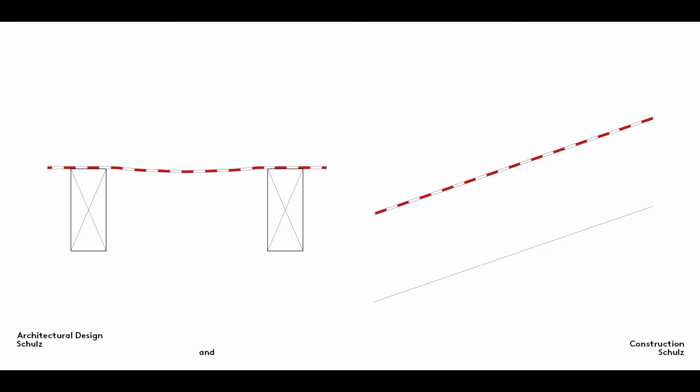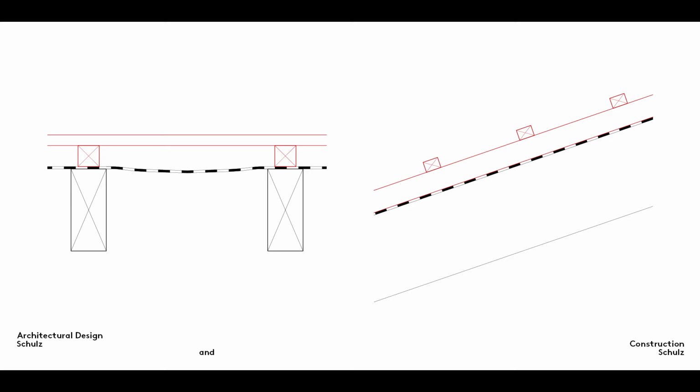The membrane is tacked or stapled onto the rafters so that it sags a little between them. At the next stage, the roofers lay the counterbattens on top of and parallel to the rafters to ensure that the roof is ventilated from the bottom up. The battens, sometimes referred to as the main battens, are then laid at right angles to the counterbattens. Batten spacing depends on the type and size of the tiles to be used.